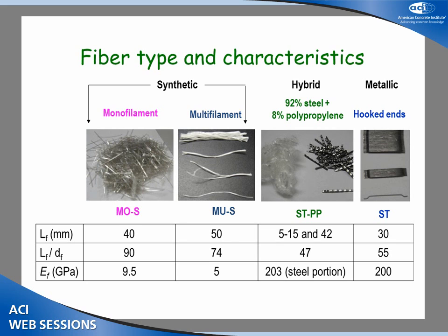All the fibers, especially the steel fibers, were fairly short in length, like 30 millimeters, because of the congestion that we often would have and the limited spacing of the rebars on both sides in repair applications. So the idea was, how do you incorporate fibers in concrete? How do you test them? What are the mechanical properties? What are the shrinkage characteristics? What is the structural performance? All of that.